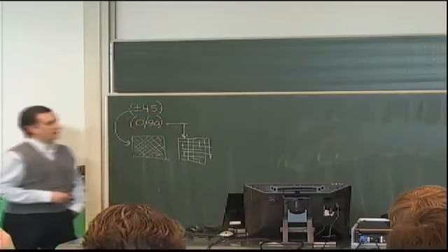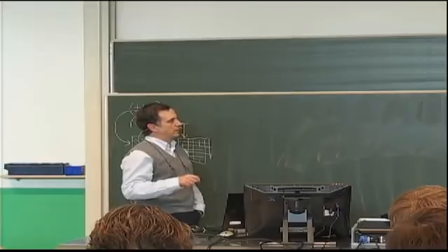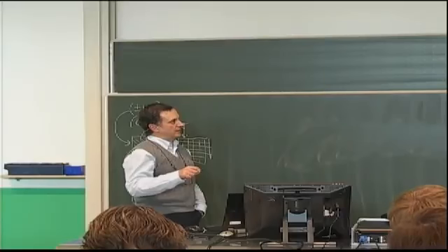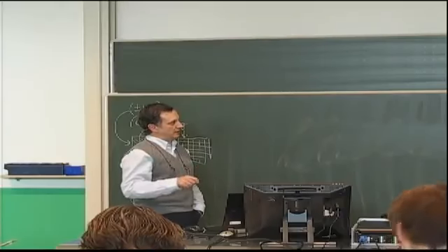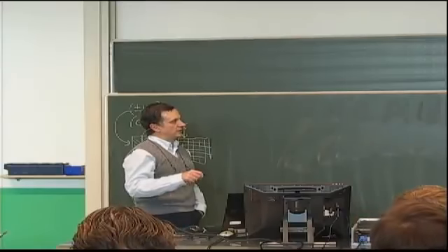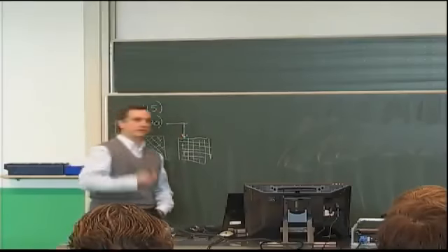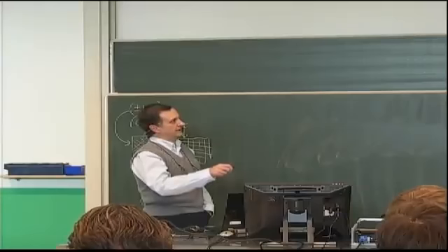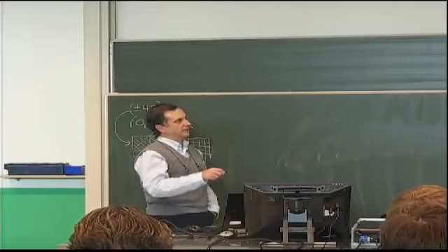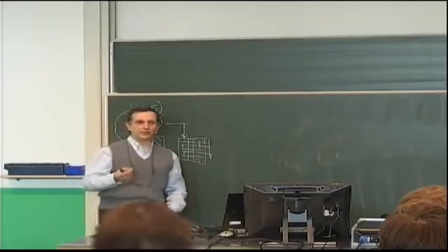And one thing we already observe is that we get to that far field value of 1 at about half the distance away from the point of action. So at about 0.4 or so, in fact at 0.3 even, we are already very close to the far field value. So whatever effect this point load has, it's really significant only within the first 30% of the distance from one edge to the other. So this is an indication of the kind of reinforcement you would need.